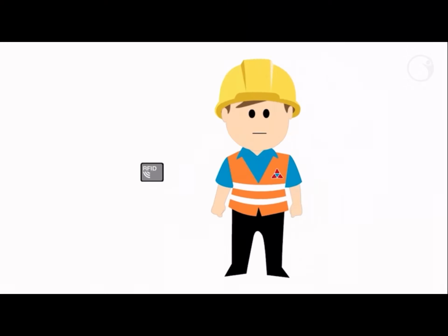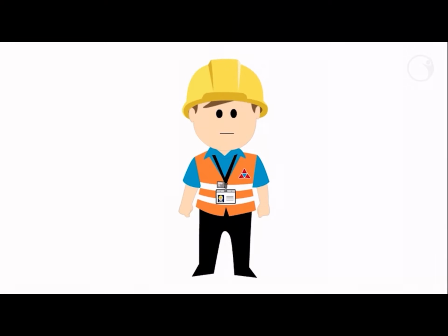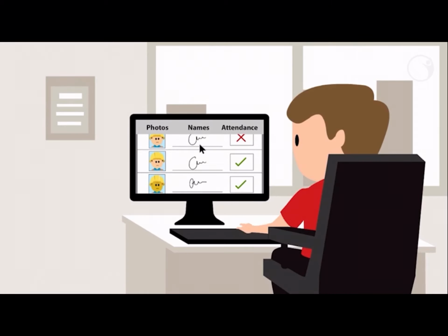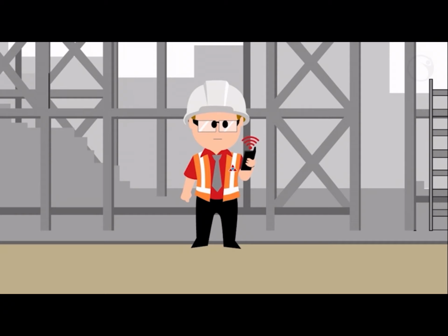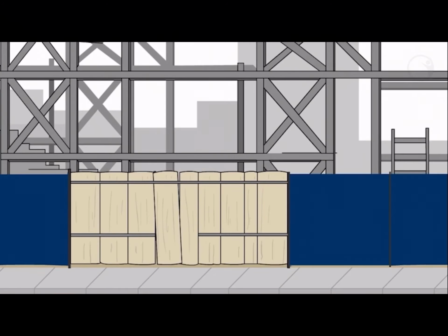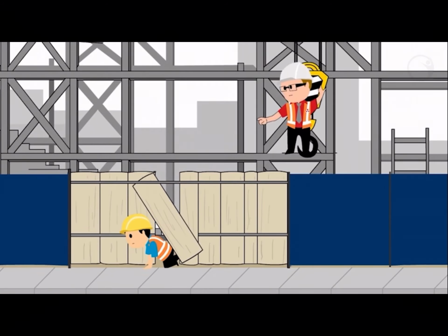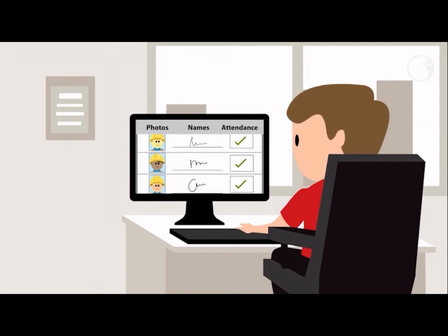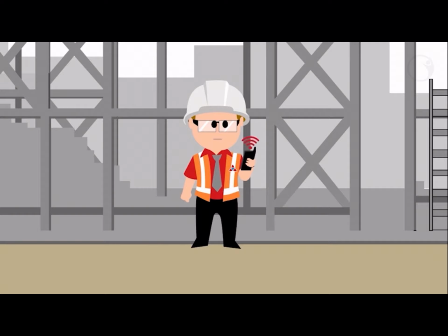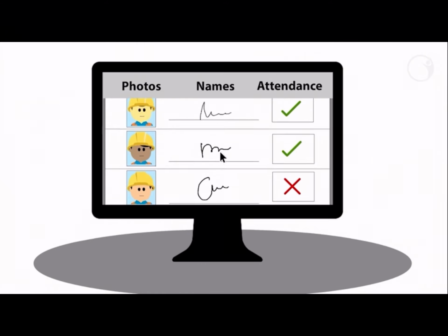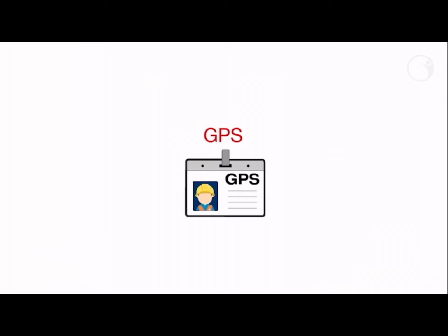RFID-based tracking. A unique RFID tag is fixed to the worker's ID card or their uniforms, camouflaged on the collar or behind the logo in the chest area. The RFID reader fixed at the client site or carried by the supervisor will keep track of their attendance. Any miss or mischief is immediately noticed, and their attendance is updated to the central database through mobile connectivity on the reader. This data is now available via cloud to anyone who needs it.